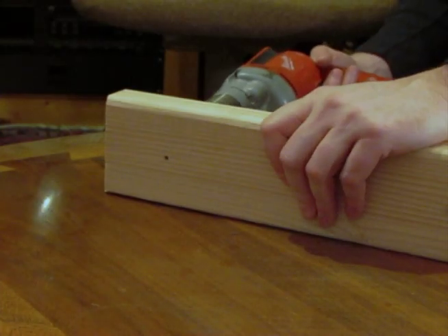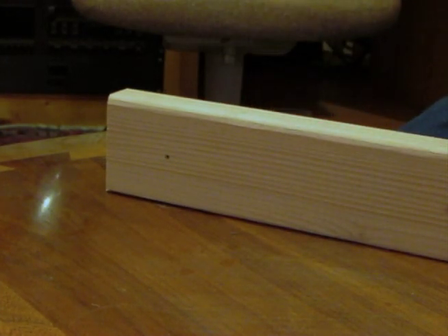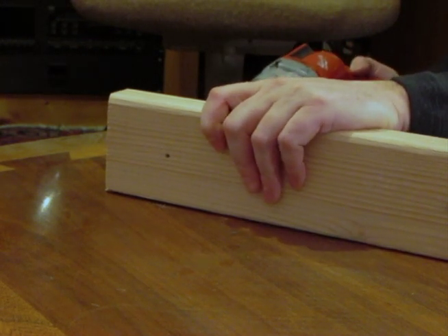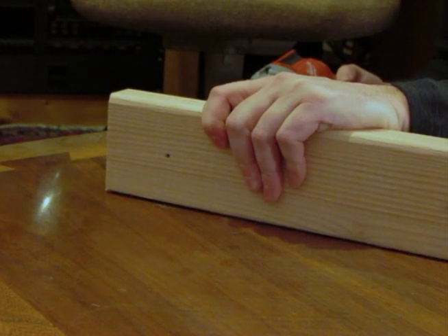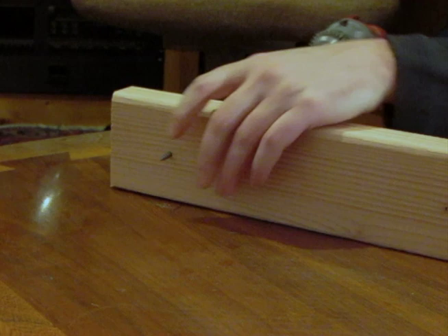In order to facilitate installation of these pieces, it pays to pre-drill the holes for the screws and to start the screws in the wood so that the tip of the screw is just starting to peek out the other side. If you're working by yourself or with another person, this makes the installation a lot quicker.